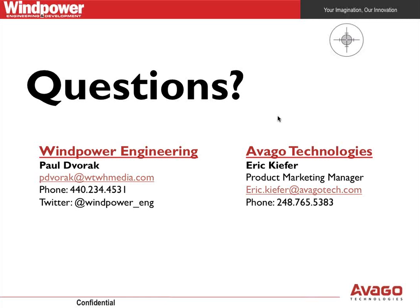For glass, actually, the windows, if you'll look at our parts, you notice I said 820 nanometers and 1310. There are very nice windows of glass transmission of light at those windows. Even better is 1550, which is what they use for long-distance telecommunications. So at these windows, and as you step up from 820 to 1310 to 1550, you get more and more efficiency in how the light is carried.